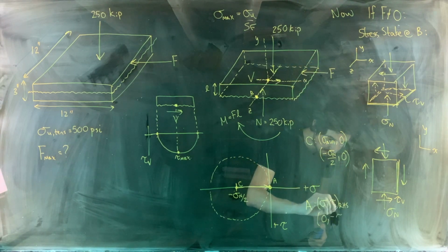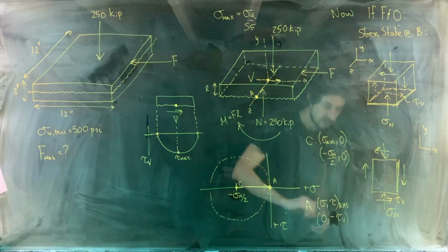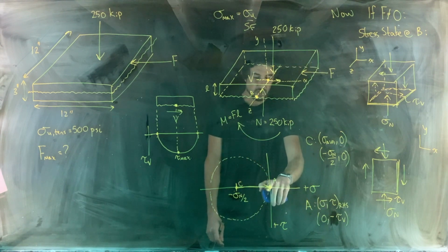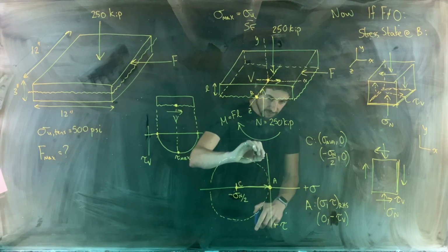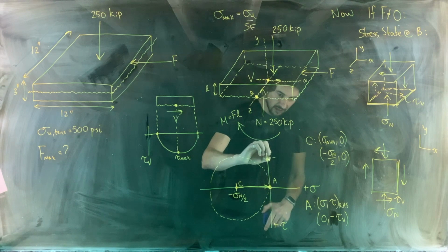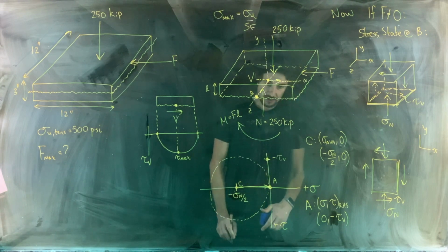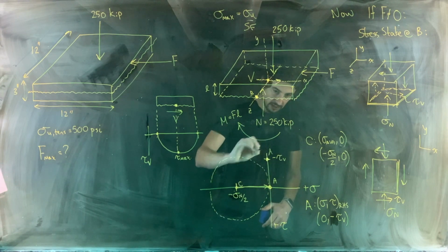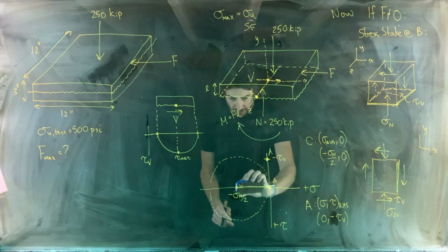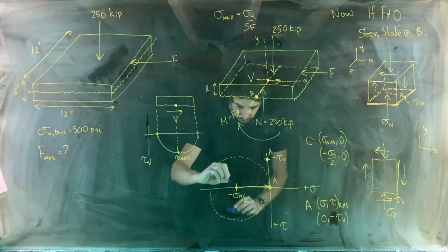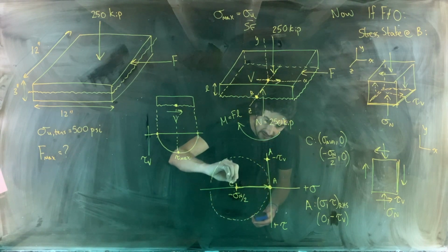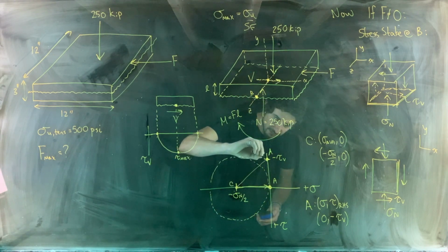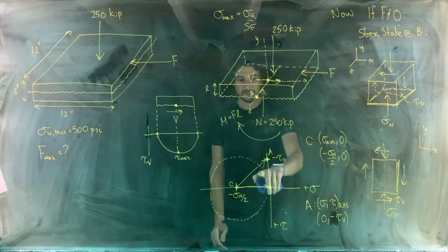So we've got negative tau V here. So point A goes from being located here to being located up here somewhere at a value of minus tau V. So this is point A for our circle now, and I'm just moving my label for the center of the circle to the other side there. And now the radius for this circle extends from C to A like this.